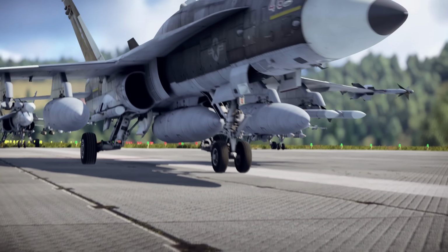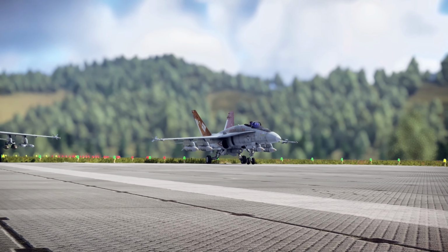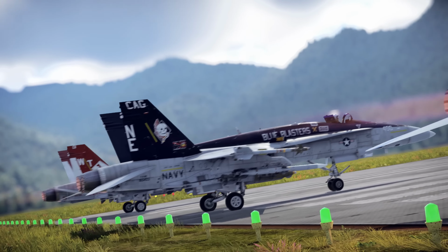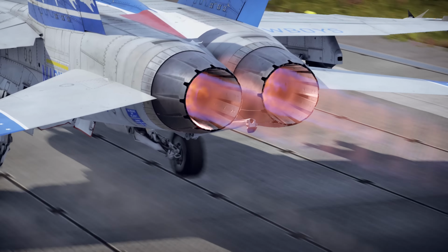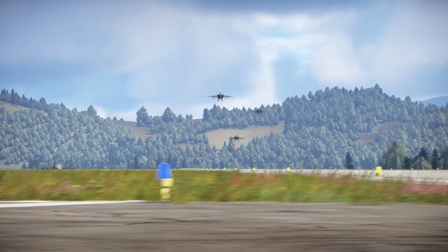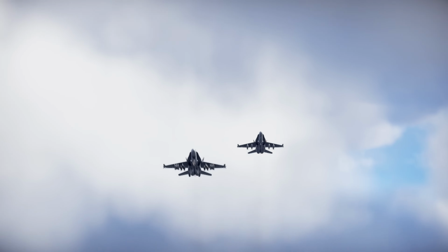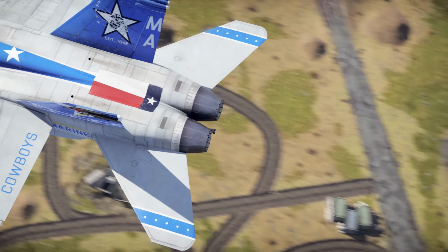To boost thrust for military aircraft, engineers took a different approach. That solution was the afterburner, a combustion section placed between the turbine and the nozzle. Additional fuel is sprayed and ignited there, dramatically increasing temperature and thus exhaust velocity.